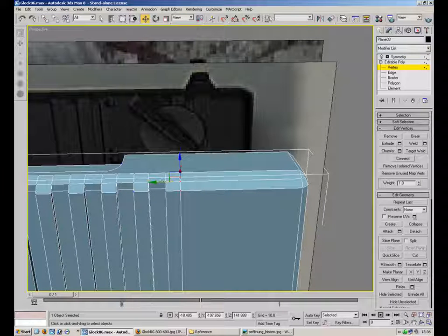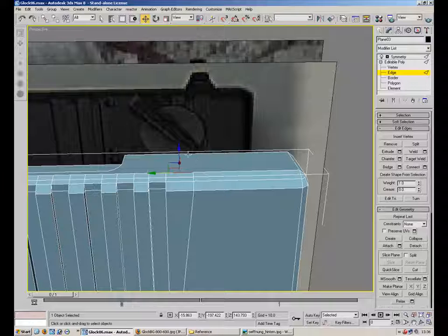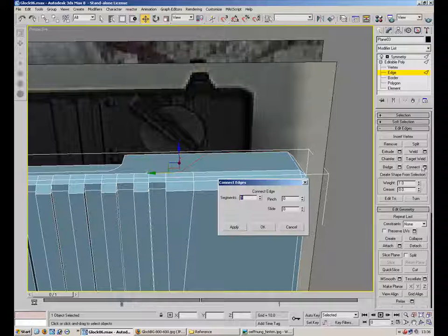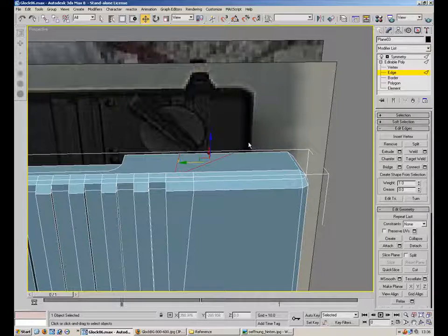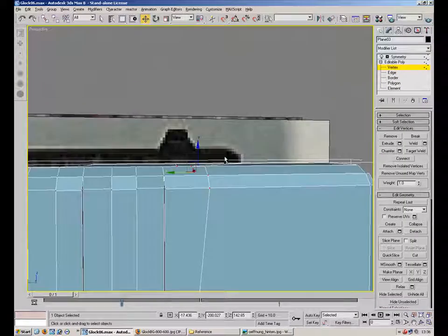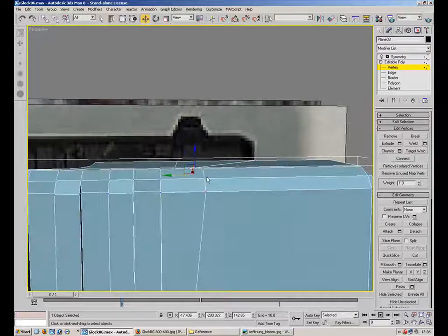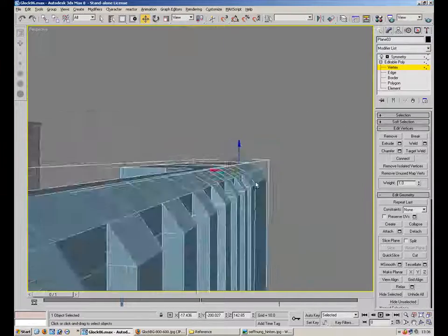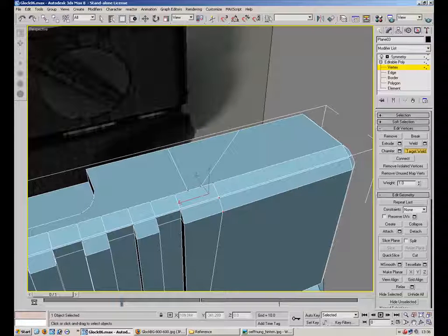I'm going to use this little bit of geometry which I've already got here, and then I'm going to select this edge as this edge, connect all 2 times. Okay. Alright, the rear sight actually looks as though it's coming out of the gun and properly attached sort of inside. So I'm going to model it out of the gun rather than as a separate object. So I've just connected those 2 verts which I've just created onto here and onto here, and then I'm just going to go through and position them in the Y coordinates to make sure they're nicely lined up and square.